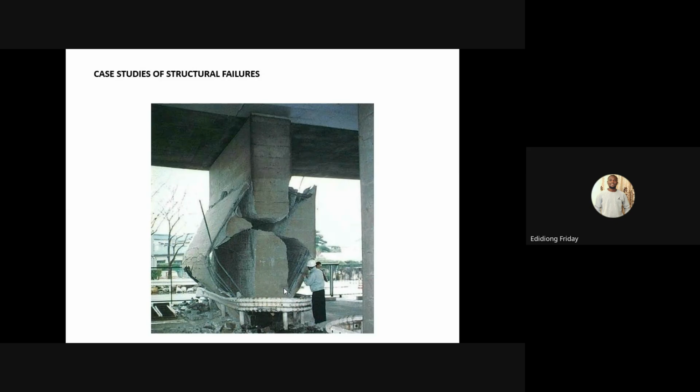Okay, so like I said again, the options are either to completely demolish and reconstruct, or partial demolition and patching up, or attending to the cracks. And then the next is retrofitting, and finally you could introduce new piers just beside them to make sure they carry the load.